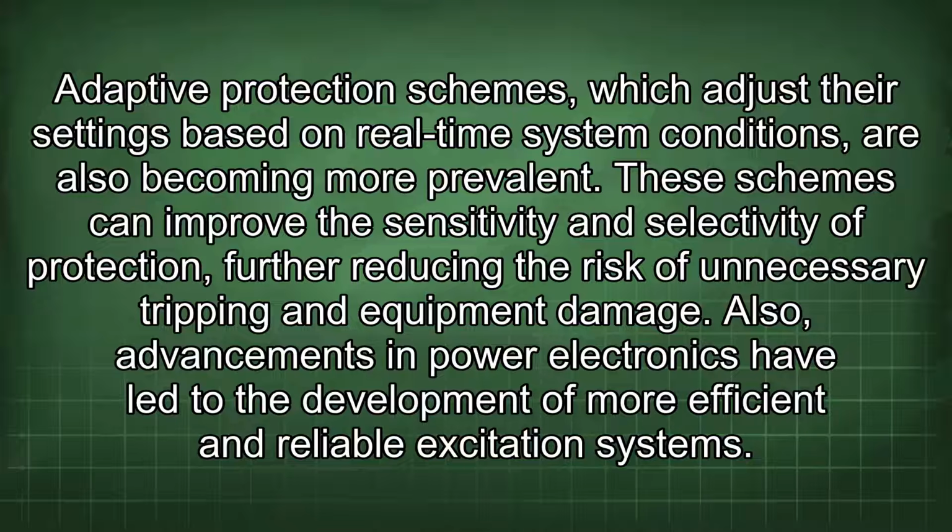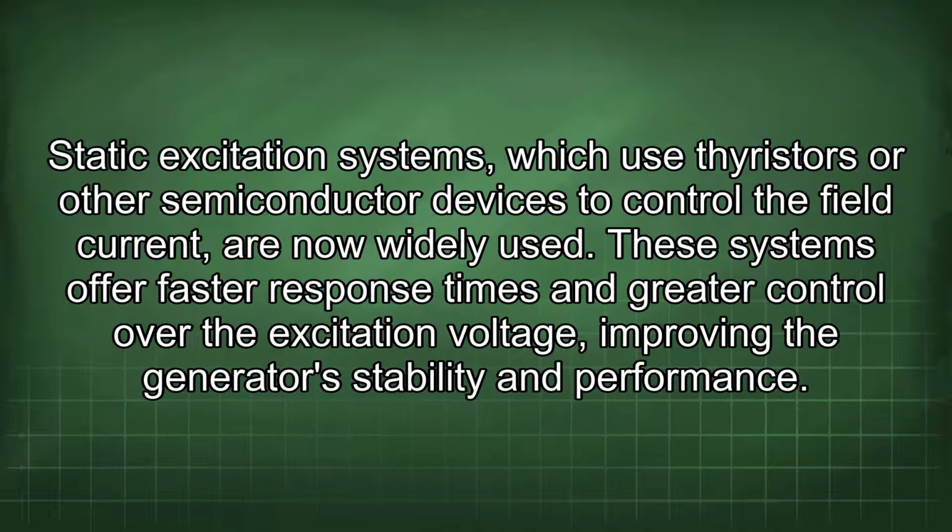Also, advancements in power electronics have led to the development of more efficient and reliable excitation systems. Static excitation systems, which use thyristors or other semiconductor devices to control the field current, are now widely used. These systems offer faster response times and greater control over the excitation voltage, improving the generator's stability and performance.